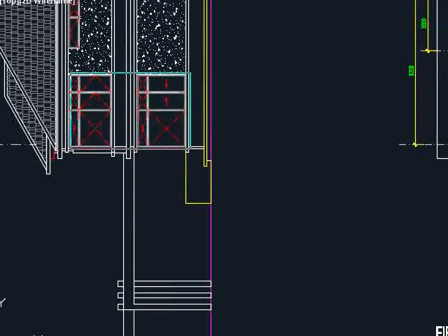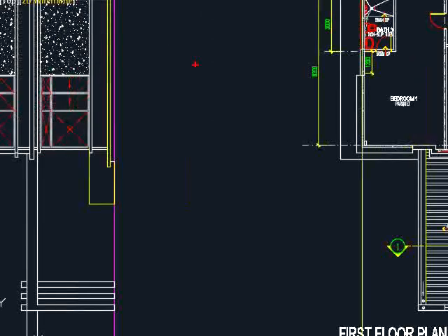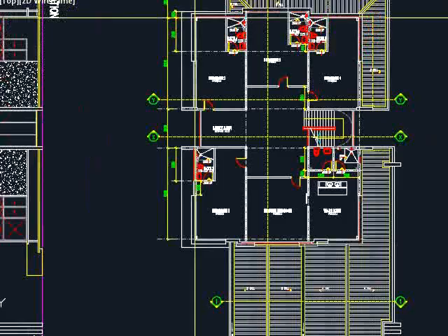Also, you need to check whether there is a continuous window for you to decide whether you're going to put the beam below the windows, or you need to give an offset distance from the window, not to clash into the windows. In fact, there are many modes that you require comparison, which you need to read more than one plan concurrently, especially when you need to propose the key plan, as well as consider the positions of the columns, which may clash into some building elements and affect the aesthetic view of the building.